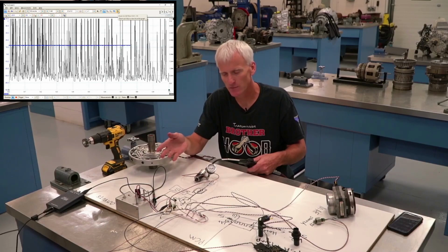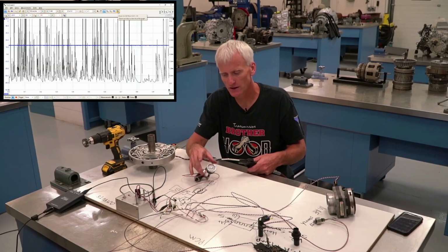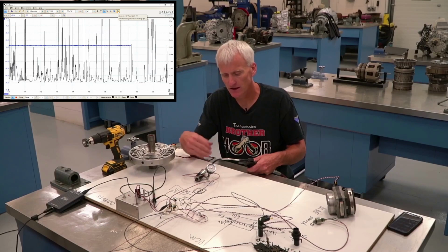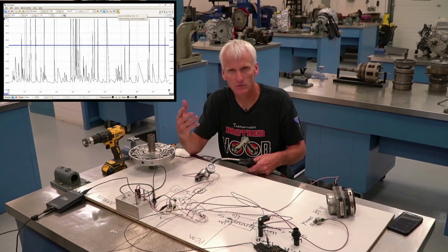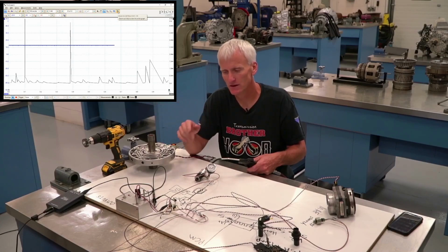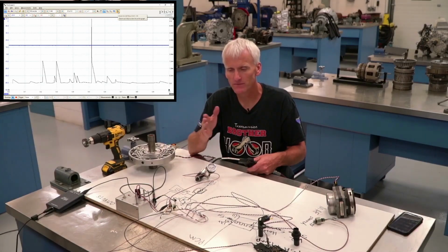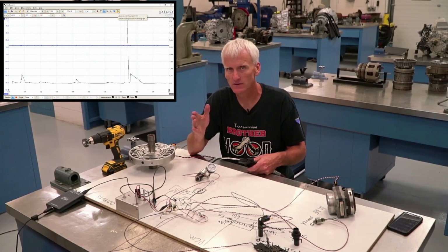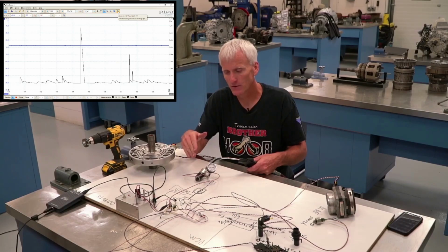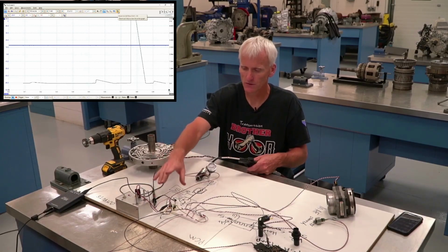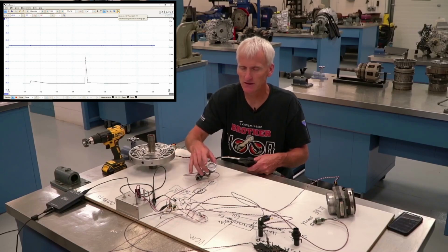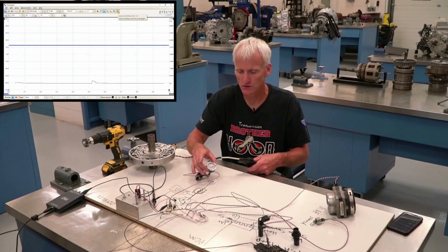This isn't the best example because what they normally do in a computer control solenoid is they operate the solenoid at a constant frequency, let's say 300 hertz, and then they vary the duty cycle, how much on time it is. This little box right there, it doesn't really change the duty cycle, it just changes the frequency. So I'm not getting the exact same effect, but rest assured, if you're doing this and the computer's in control of it, it changes the duty cycle, the amount of on time to control the solenoid.